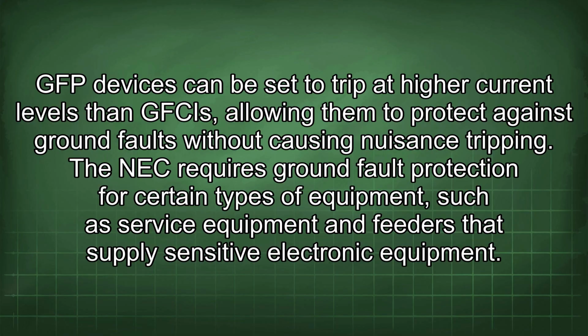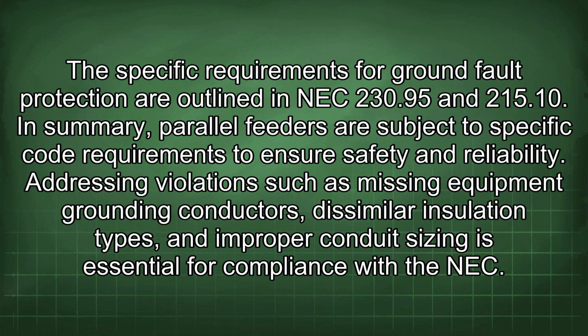The NEC requires ground fault protection for certain types of equipment, such as service equipment and feeders that supply sensitive electronic equipment. The specific requirements for ground fault protection are outlined in NEC 230.95 and 215.10.